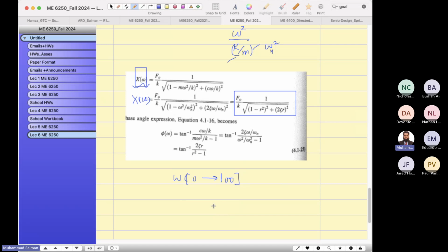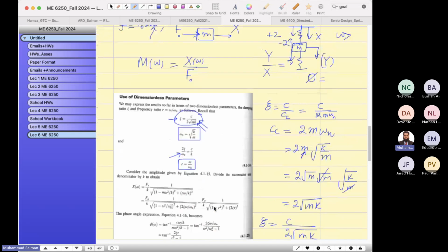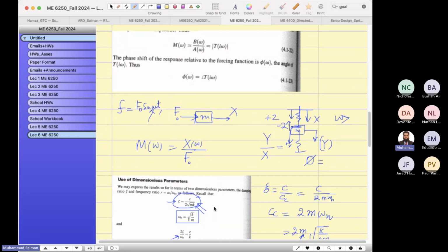Just to tell you that at high frequency, this mass starts reducing the distance. Suppose I'm giving input like 2 centimeters from the top, but it will not move that much at high frequency. It will move maybe 0.3 centimeters. As you go increasing, like if you see my hand, I am giving input here like this, and then the mass starts reducing its displacement at a high frequency.